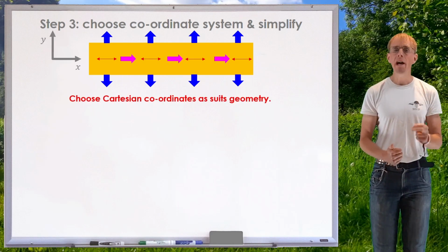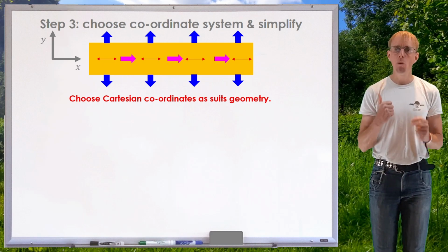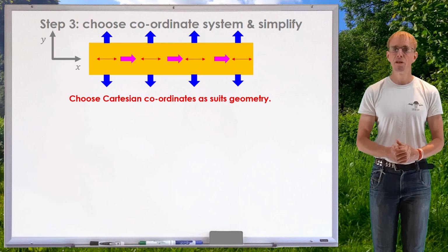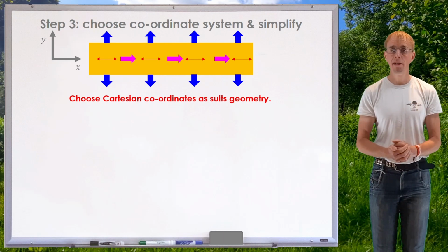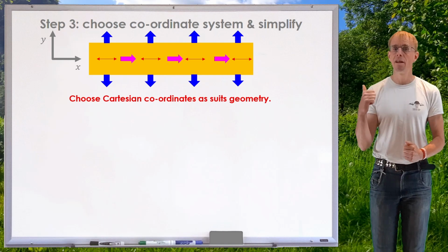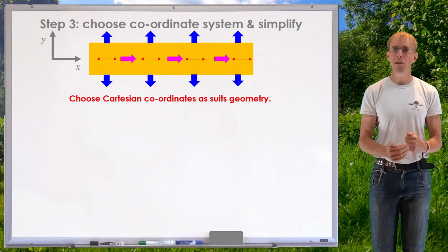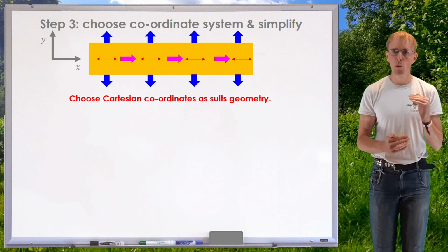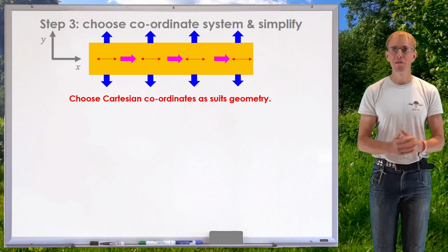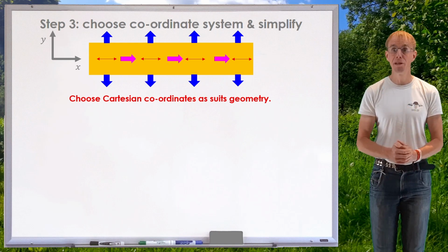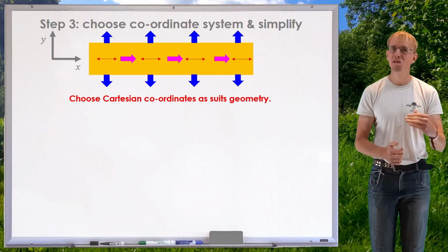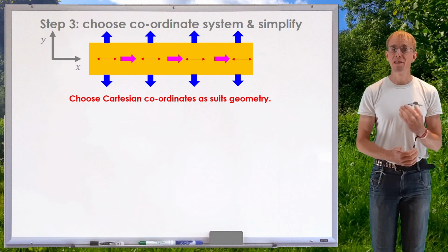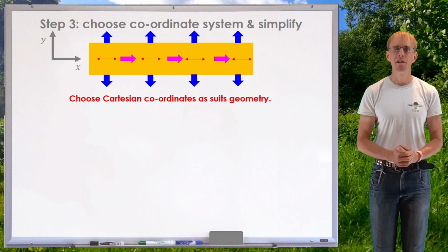Perfect. Now, where I am placing my axes is quite carefully chosen, because if I assume that the convective heat transfer magnitude is the same on the top of the film as it is on the bottom of the film, I have centerline symmetry of this problem. And if I place my x-axis on that symmetry line, that makes the maths a heck of a lot more straightforward, because on that symmetry line, I would expect there to be a turning point in a temperature profile, which infers zero gradient. And since I'm going to be solving ordinary differential equations, if I have a zero gradient at y equals 0, that's kind of nice to use.